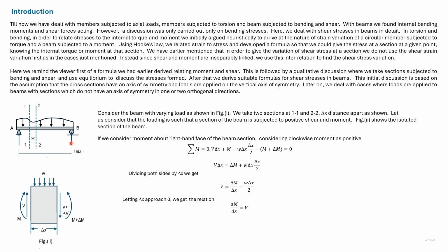So consider this simply supported beam with arbitrary loading. We consider 2 sections 1-1 and 2-2, which are del x distance apart. This section is shown here with the loads acting. We assume that both the shear force and the moment acting are positive.